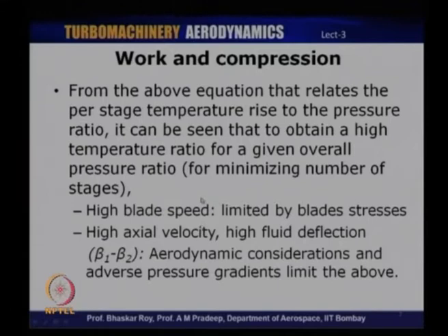High blade speed is limited by the blade stresses, and high axial velocity or fluid deflection is limited by the aerodynamic performance penalties one may have to pay, and also the adverse pressure gradients. If the fluid deflection is very high, the fluid is forced to take an increased turn, which leads to increased adverse pressure gradients, and the performance of the compressor blade would be drastically affected.